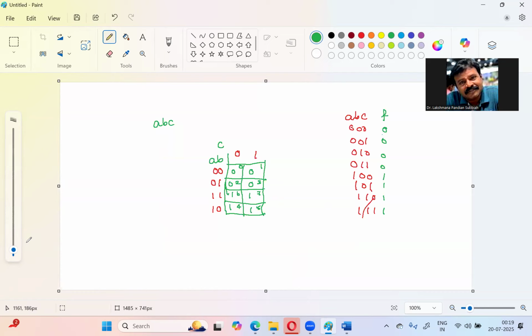Now you want to realize the function with Boolean algebra, then here we have to consider the maximum possible combinations of 2's, 4's, 8's, right? So here we now have 4 ones combined together. The 4 ones are in adjacent cells, so we can combine them together. Then we have only one term realized. So what's the term now?